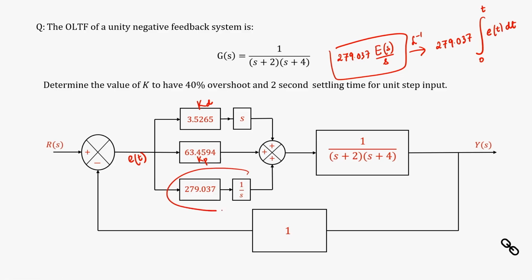So, that means this part is acting like an integrator. So, this is an integrator, right, 1 by s is an integrator, s is a differentiator. So, 1 by s is acting as an integrator here, 1 by s is integrating e(t), and that is the output here. So, the output in this case is an integration of the error signal multiplied by this constant value. So, therefore, this is called an integral controller. So, we have proportional, which is the P part, we have integral, which is I, and derivative, which is D, and this is why we call such a controller a PID controller.